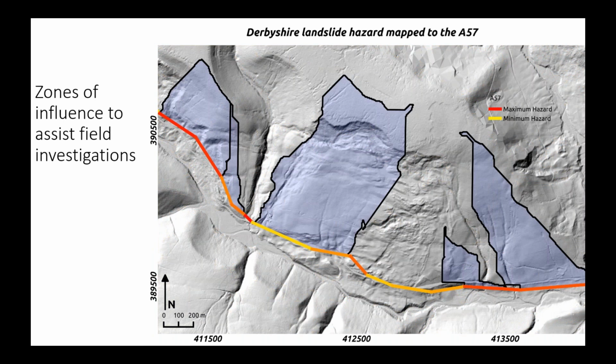One of the things we became interested in was trying to use our flow routing algorithms to map the upslope areas of influence onto segments of infrastructure networks. So we use a segmentation type of algorithm to split the linear features, such as roads or rails, into segments, and then we can look at all the pixels that drain onto those segments, and we can calculate the probability of having cells that are risky in terms of having a higher chance of being prone to failure.